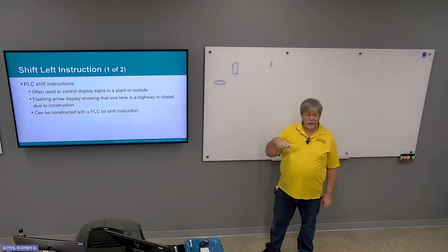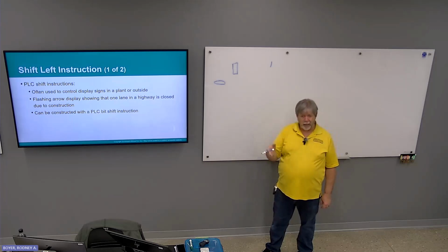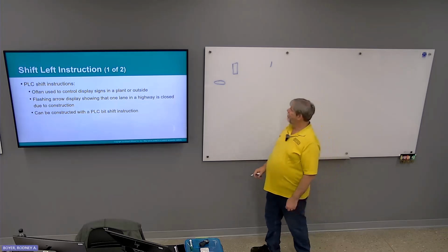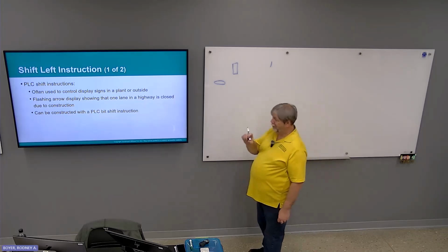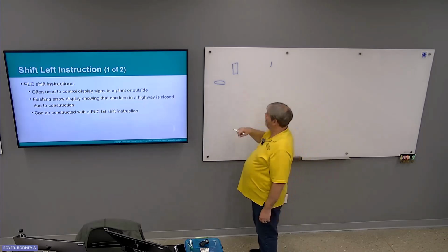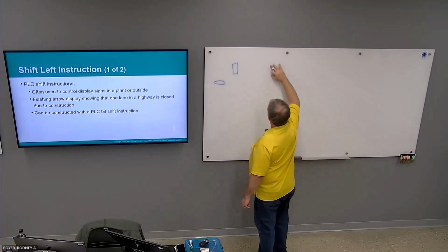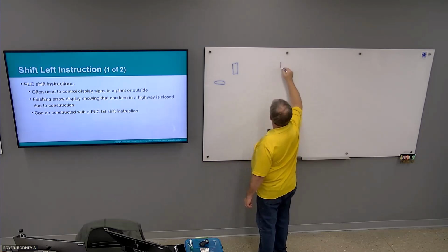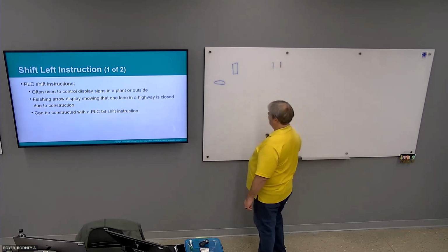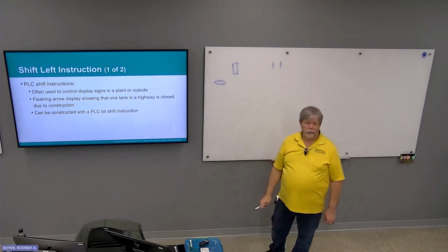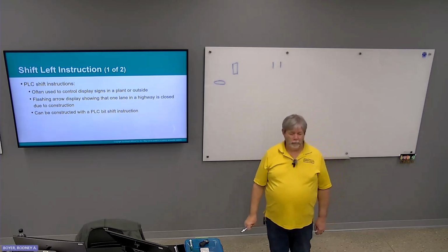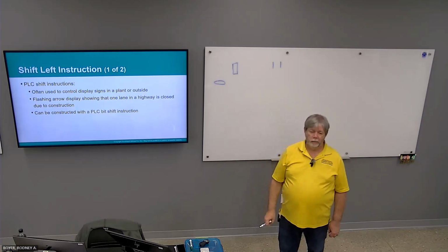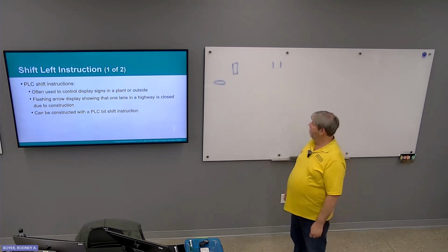This type of application you'll be running on a timer, so every couple of seconds or whatever, you expect to see a bar of soap. So timer done, bit set, go look at the switch. There's another bar of soap there. I'm going to move that one down and bring another one into my register. The timer times out again a couple of seconds later.